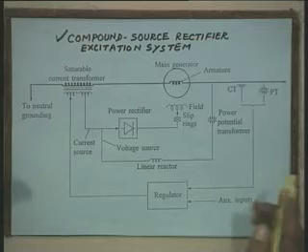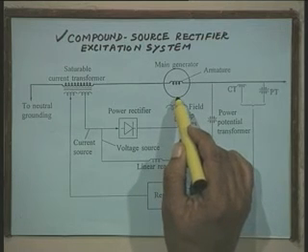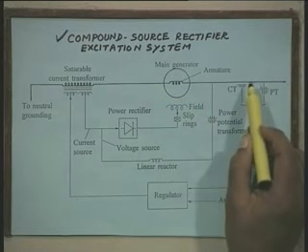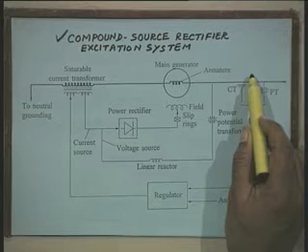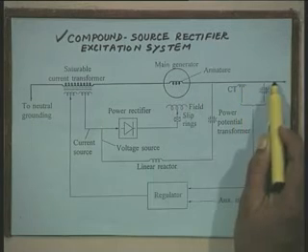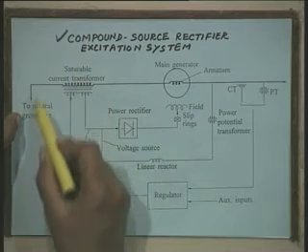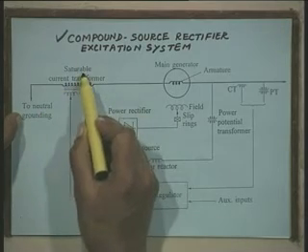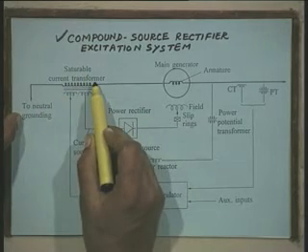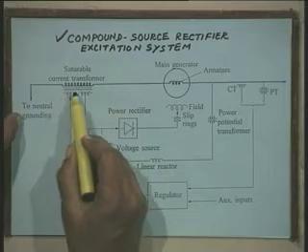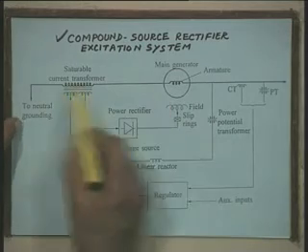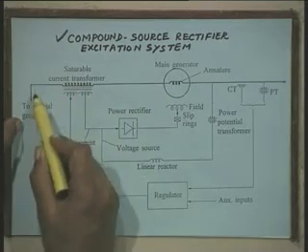the field current in the main generator is made a function of the terminal voltage of the synchronous generator and the load current. Therefore, in this arrangement, we make use of a transformer which is called saturable current transformer. This saturable current transformer is connected in the neutral circuit of the main alternator.